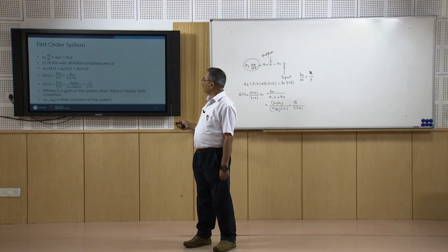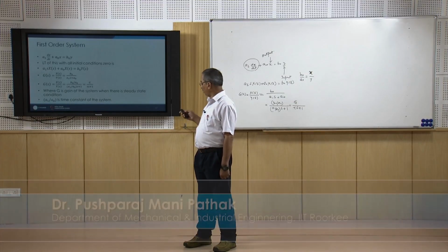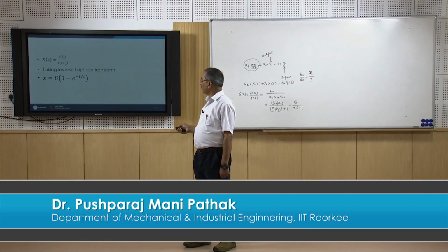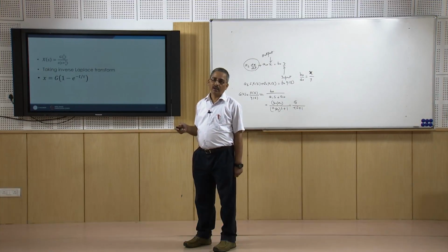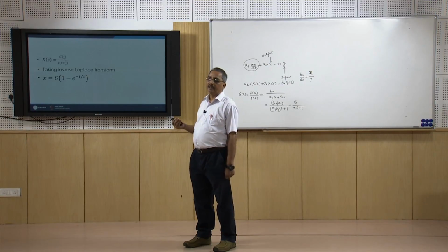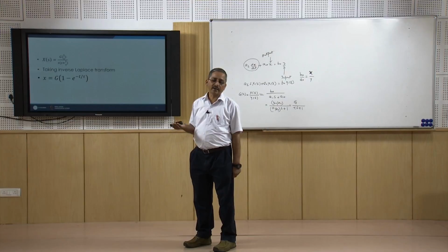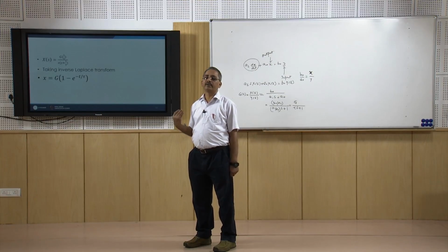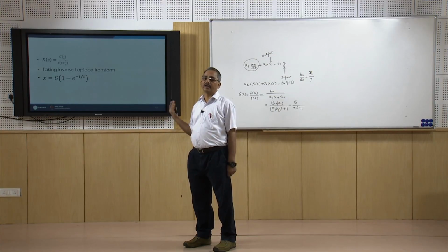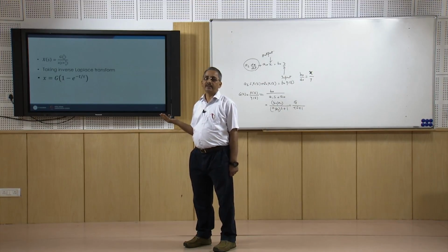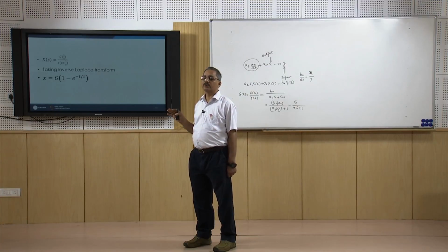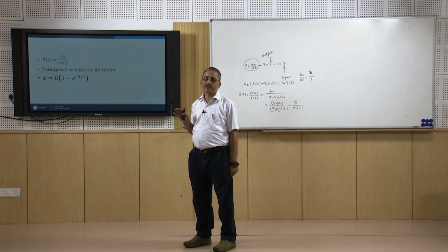So, the application of the transfer function is that for a given differential equation we can find the output response without solving the differential equation. Using the Laplace transform we convert the differential equation into an algebraic equation, manipulate it, and then convert it back from the S domain into the time domain using the inverse Laplace transform. This way we can find the response of the system.